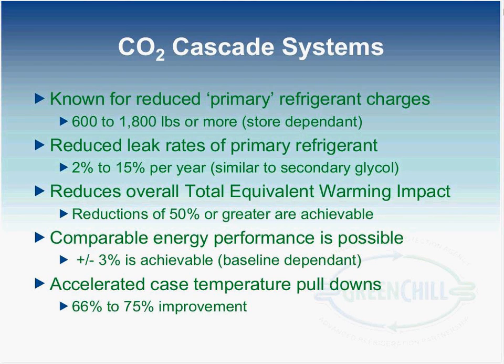Next would be accelerated case temperature pull downs, anywhere from 66 to 75% improvement over traditional times for pulling cases down to temperature after defrost. What we have seen time and time again with CO2 is that cases can pull down to temperature in the matter of 15 minutes after defrost, versus the 30 to 45 minutes that it takes today after a defrost cycle. So that means less shock on your product and improved case temperatures, or longer time spans with cases being at temperature than what you would have traditionally with a standard DX system.